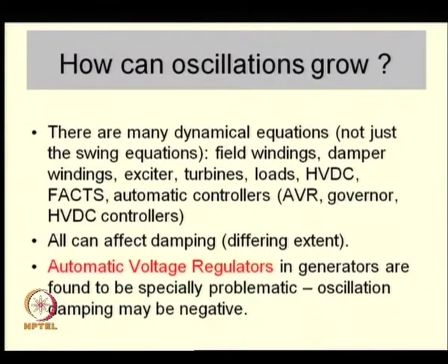Of course, the question comes that it seems almost counterintuitive: why should oscillations grow with time? Remember that relative angular motion between synchronous machines, I discussed by using a very crude and simple analogy: synchronous machines connected to each other can be considered as masses connected to each other with springs, like an interconnected multi-mass, multi-spring system. So, the question is how can the relative motion which is excited due to disturbances grow with time.